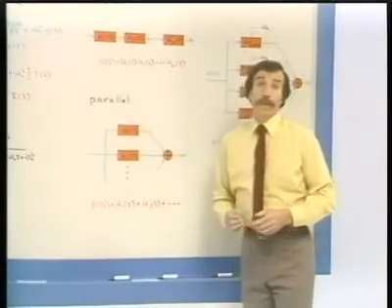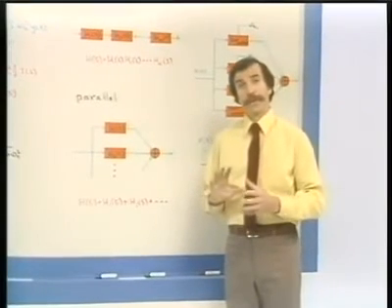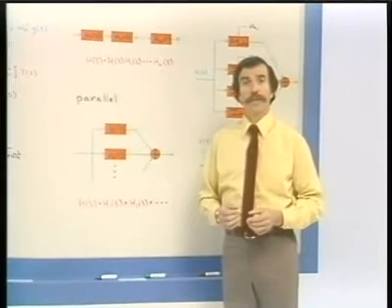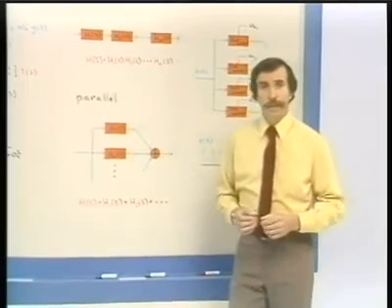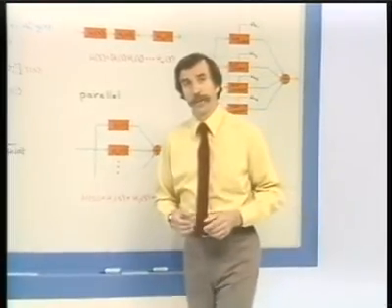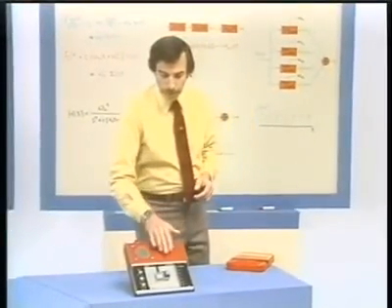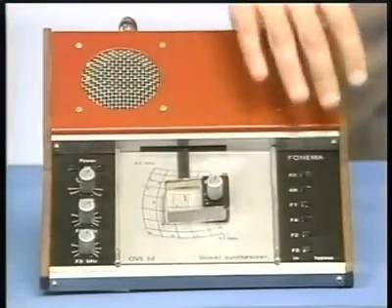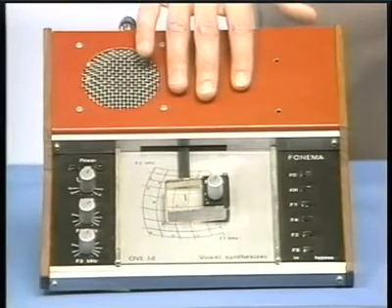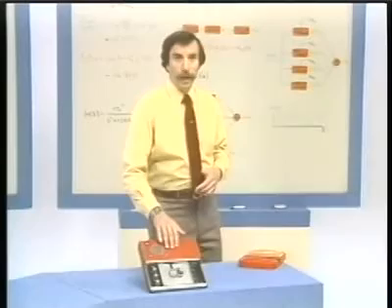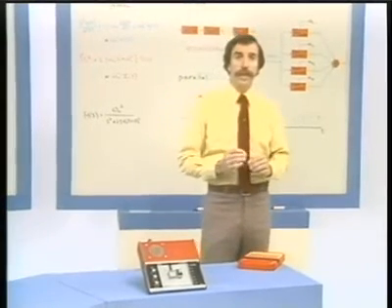One very common context in which second order systems are combined together, either in parallel or in cascade, to form a more interesting system is in speech synthesis. What I'd like to do is demonstrate a speech synthesizer, which I have here, which is a parallel combination of 4 second-order systems, very much of the type that we've just talked about. I'll return to the synthesizer in a minute. Let me first just indicate what the basic idea is.